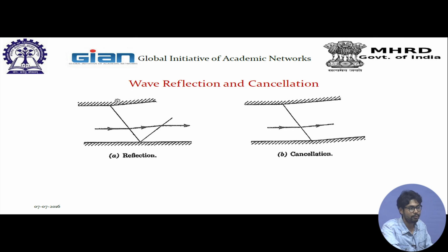Now wave reflection occurs when the boundary alignment is not in sync with the flow turning. So this is what is happening. A shock is coming and then it is again reflected. Why? Because this wall is straight here. If the flow turning is in sync with the boundary, then the shock will get cancelled, because in that case the flow has to obey the geometry anyway. So that is why this further reflection is not needed. So suppose we start with this line and then we keep on drawing the contour, ensuring that the reflection is cancelled, and in this way we will draw the contour.